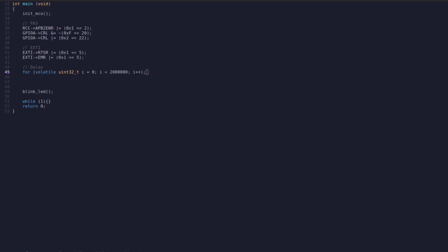Before putting the MCU to sleep, we first need to define how the MCU will be awakened. Here, in my case, I have defined port A5 to wake up the MCU by detecting a rising edge event. All these values here I took from the datasheet, so you need to look at your datasheet to see if the values correspond to your specific microcontroller.